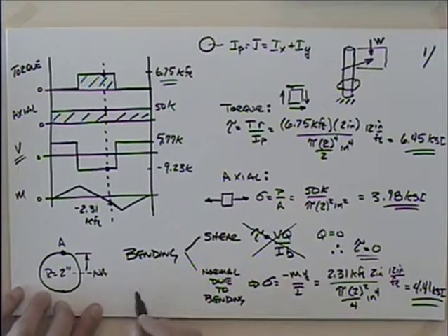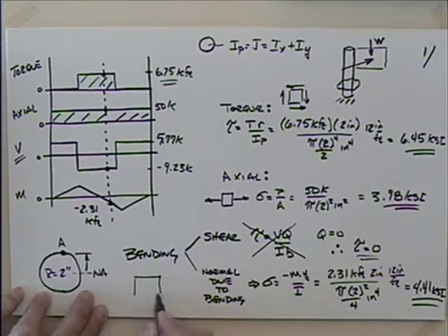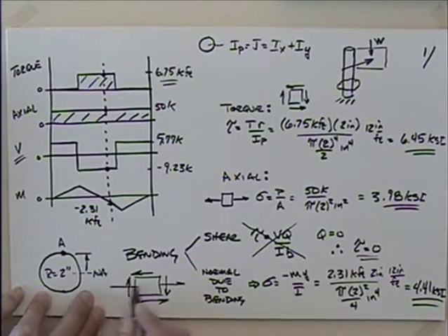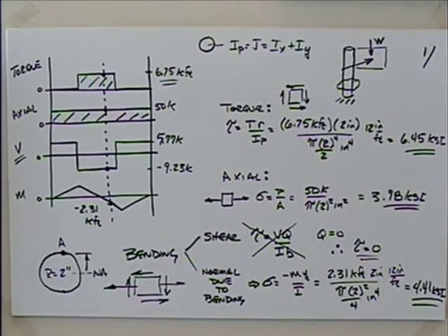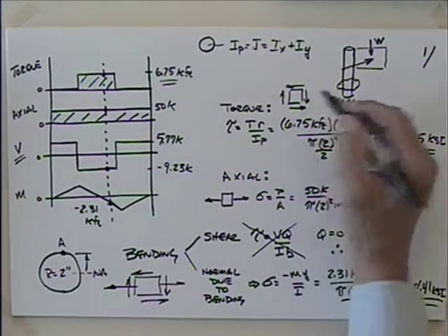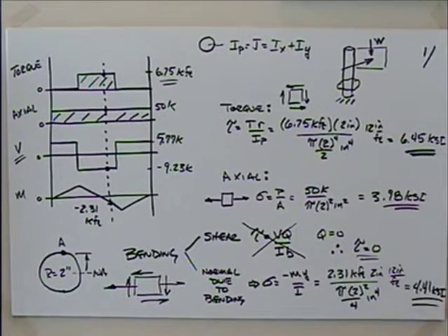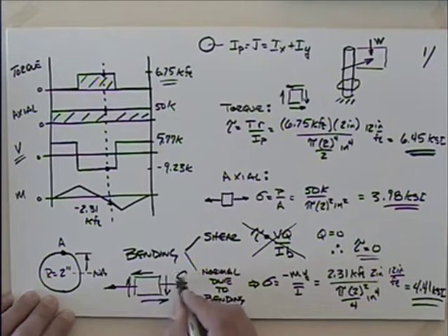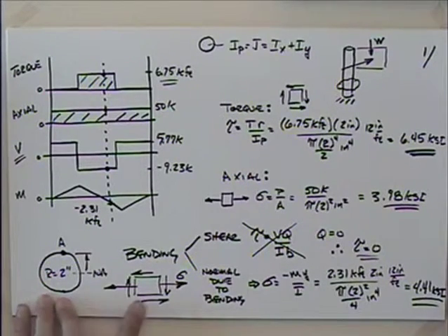So if I were to come over and put this bending onto an element, what does that look like? We'd probably have some shear due to bending, which we just found was 0 in this particular case. And then we have some normal stress due to bending. Looks like we've got that, right? So I probably need to put these together. This axial looks an awful lot like this sigma that we have down there. So I probably need to combine these, don't I?